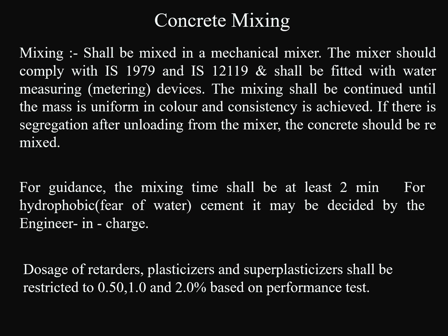For hydrophobic cement, the mixing time may be decided by the engineer in charge. Dosage of retarders, plasticizers and super plasticizers, if used, shall be restricted to 0.5, 1 and 2% based on the performance test and as recommended by the respective manufacturers.